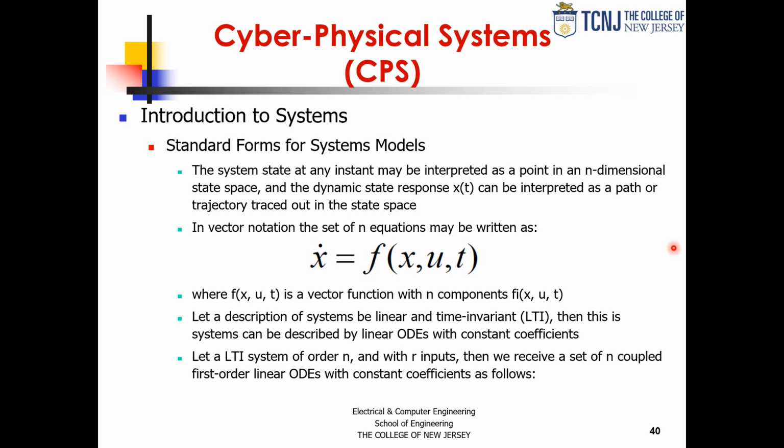What is a state diagram? You remember that. What is a state diagram? Well, that is the state space time trajectory. Start at state 0. If this happens, I go to state 1. If this happens, I go to state 2. If not, go back to state 0. That is a trajectory in the state space as you go through time, as you go through the different clock cycles. That is very relevant to today's design of digital systems and also to the design of software. Because as I mentioned, one of the tools and methods to implement some software, depending on the application, is as a state machine.